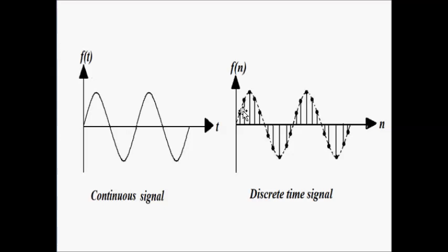The amplitude values are not taken into consideration. Basically, this technique is used for analog signal to digital signal conversion by a process called sampling, which we will discuss in some other video in detail. So this process is called sampling, where we take the amplitude values only at certain specific points for converting it into a digital signal, following the Nyquist criteria.